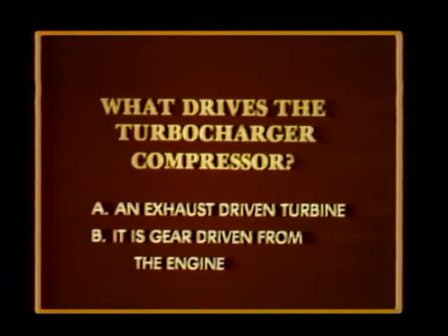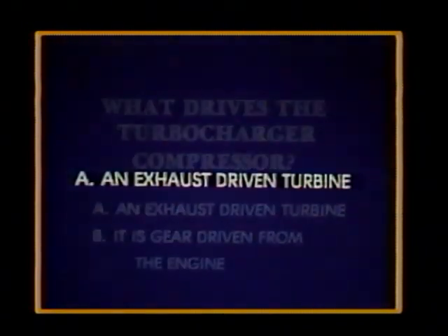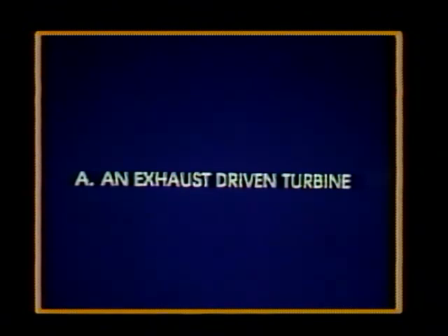Finally, what drives the turbocharger compressor? Is it driven by an exhaust-driven turbine, or is it gear-driven from the engine? A turbocharger compressor is driven by an exhaust-driven turbine. Spinning the turbine causes some back pressure, but the loss is more than regained by supercharging.